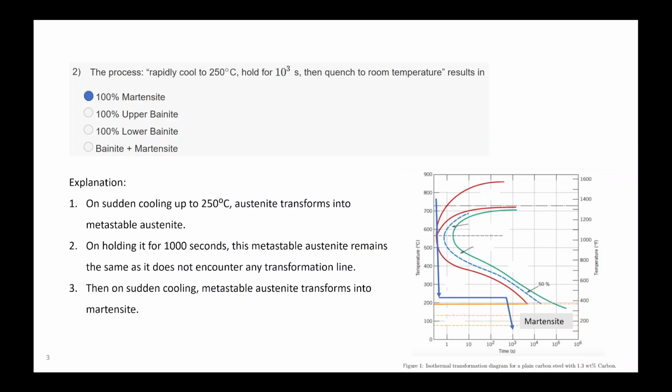Up to necking, in case of gauge length, your length will be changing homogeneously in the entire length. But as soon as you start forming a neck, there will be a localized formation, an abrupt change in cross section. So if a neck has formed, after that it won't be homogeneous. Your strain will be concentrated in that region, so there will be a triaxial type of stress concentration there.